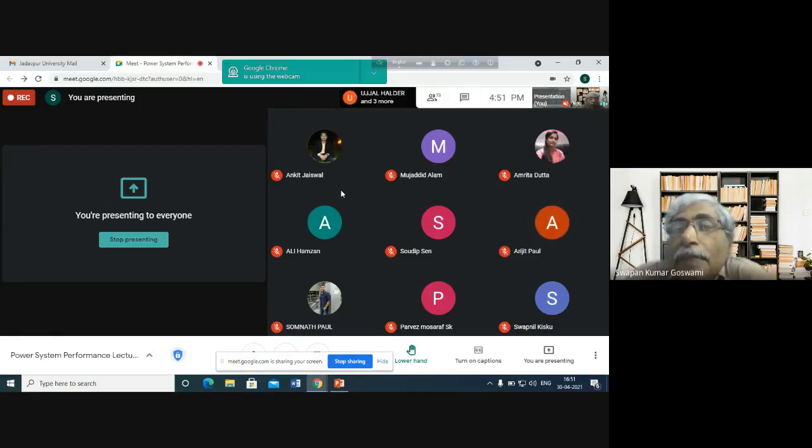Actually, stranded conductor, they are spiral. A group of conductors, they are spiraled together. Each conductor is above the other conductor like this, and they are spiraled together. What is the main purpose of spiraling in this way? Only to increase the flexibility. Each conductor is composed of a number of subconductors.